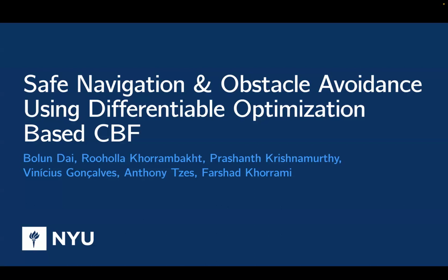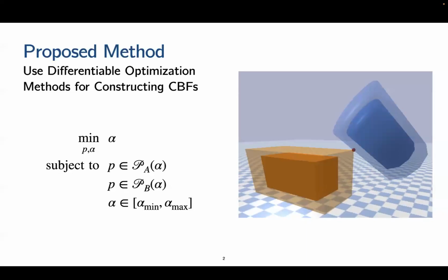I'm pleased to present our work on safe navigation and obstacle avoidance using differentiable optimization-based CBF. Constructing CBFs between two geometric shapes has been a challenging task. In this work, we propose to compute the CBF for geometric obstacle avoidance tasks using a differentiable conic optimization problem.